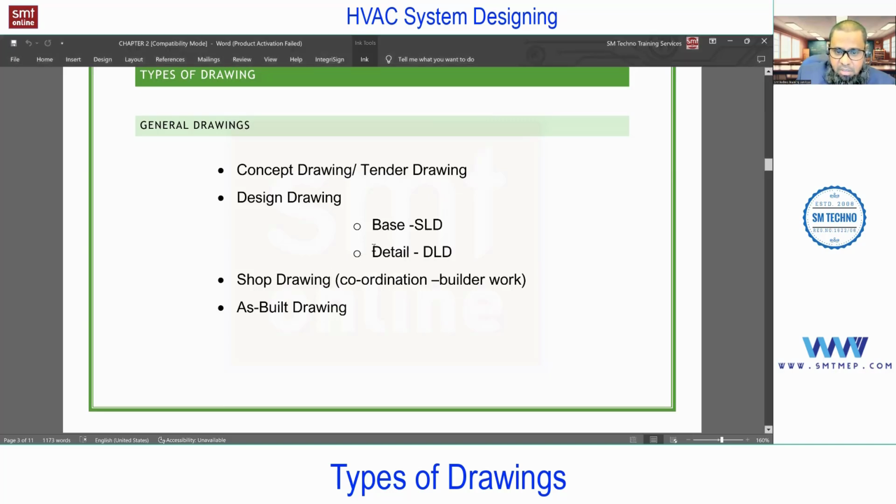Again, in the design drawing, the detail design drawing, you'll find say 70 to 80%, but this is not complete. And for a big project, the work is going to start on site with the detail design drawing only, because preparing the shop drawing will take time. So almost 60 to 70% of the work for a big project is going to be completed with the design drawing. Parallelly, the subcontracting company will prepare the shop drawing, and in the final stage they use the shop drawing. I'm talking about a big project. For a small project, they can execute the job directly with the detailed design drawing.